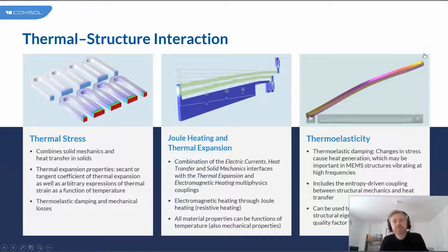You can also look at something called thermoelasticity. So where we're looking at mechanical vibration, we may have some damping within the material, and we may want to actually calculate the generation of heat due to the losses due to damping in the material. So the energy that's lost to damping, we can convert to a heat source, and we can actually calculate how much heat that will generate.